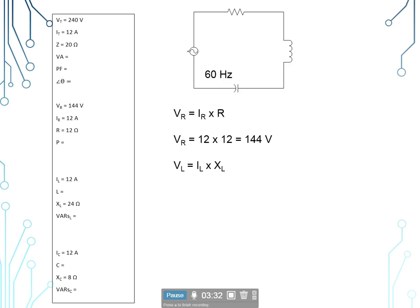The voltage at our inductor is going to be equal to our current at the inductor times our inductive reactance. So we have a current at our inductor of 12 amps times our inductive reactance of 24 ohms, giving us 288 volts.